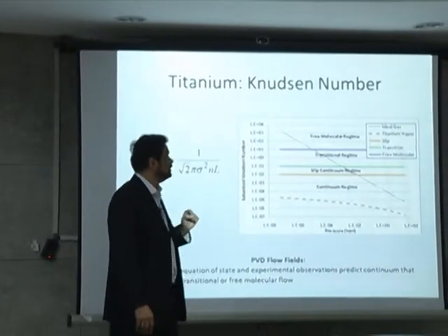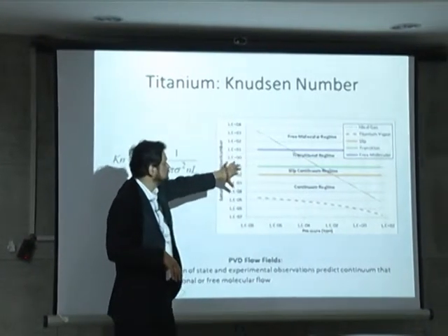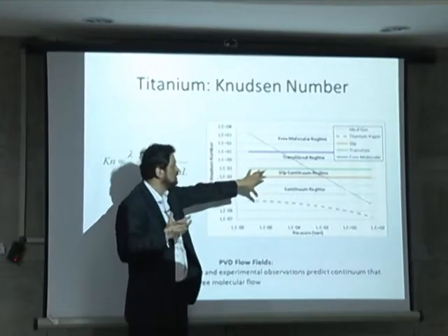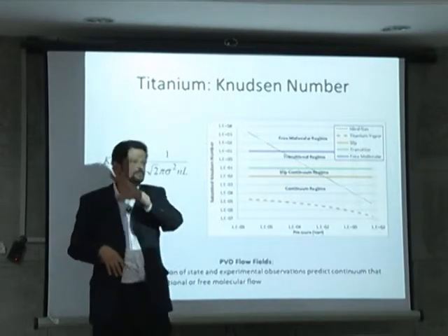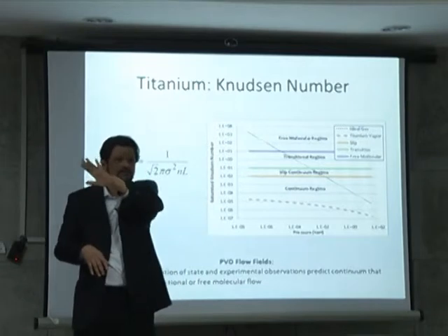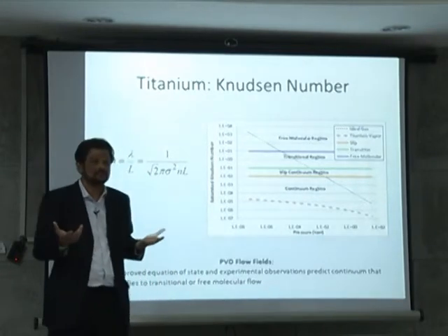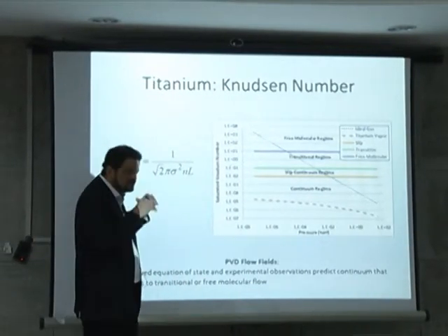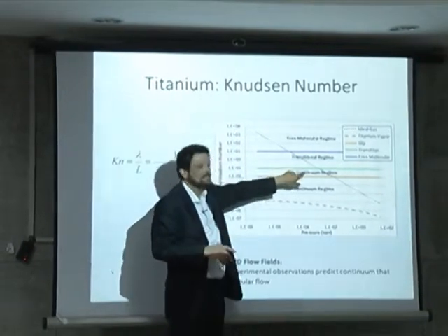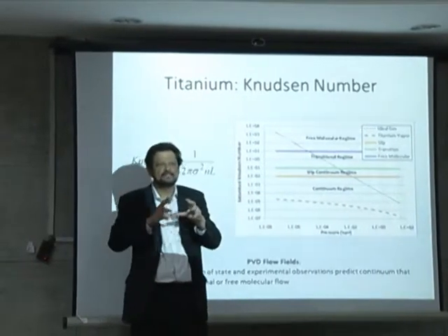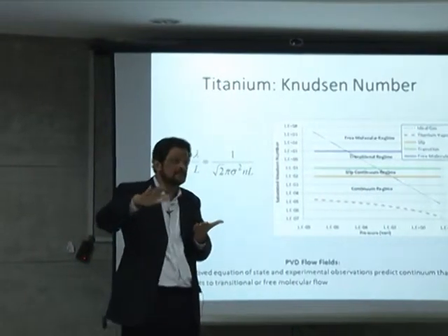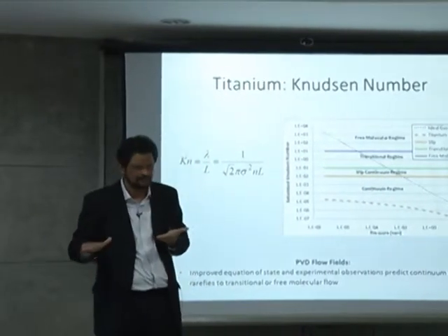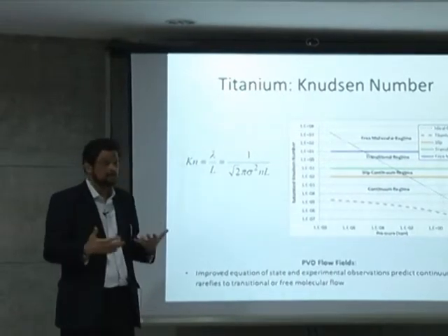Well, when you go to molecules, a particle level, it is not exactly 0, because the particles may just skip, just hit and come out. And so the speed is not exactly 0, it continues, and there is a slip continuum region. So when it is rarefied, when it's a low density region, there is some speed that can occur even at the solid boundary, which is another complication.